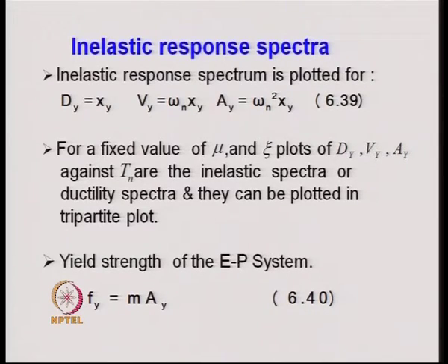That is very advantageous, because we will see later that if we know the elastic response spectrum of a single degree of freedom system drawn on a tripartite plot, then from that one can obtain the inelastic response spectrum for different values of the ductility factor mu.